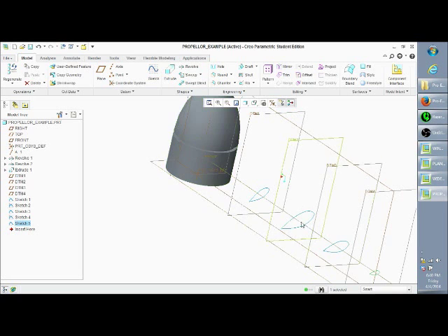about creating your blade. So now it's time to create the blend protrusion that will start from this circle that's hidden in here, and then bring it out all the way down to this last airfoil.